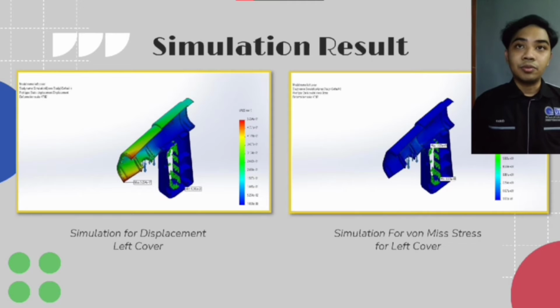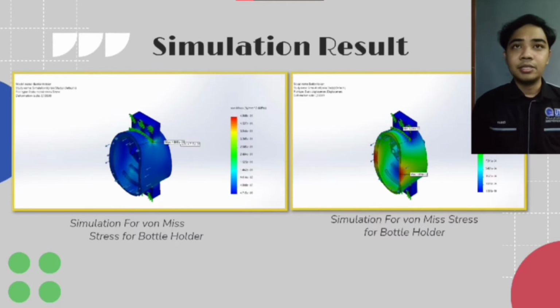This analysis needs to use the finest mesh because of the complexity of the parts. The analysis took about 0.5 hour, or in exact time 26 minutes and 31 seconds for the mesh and to analyze. After the analysis, we found that the part has the most stress earlier, and the material could not handle the stress.